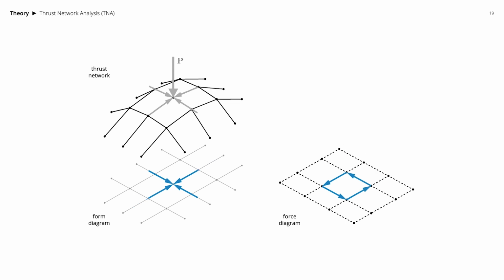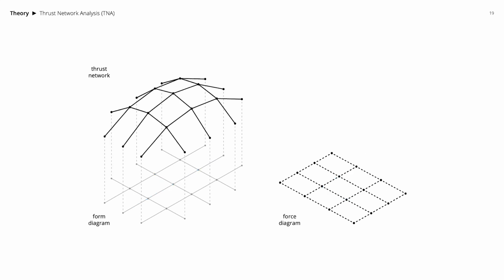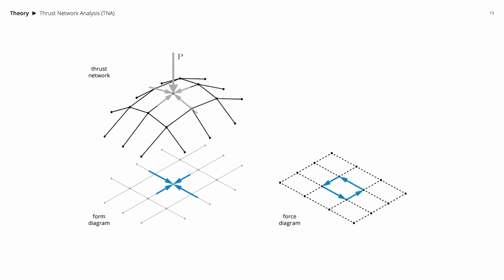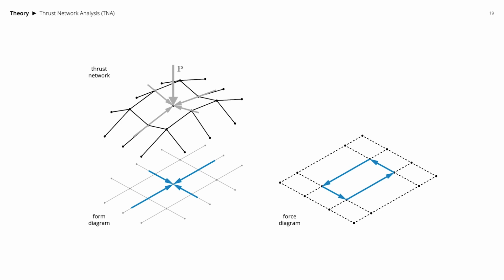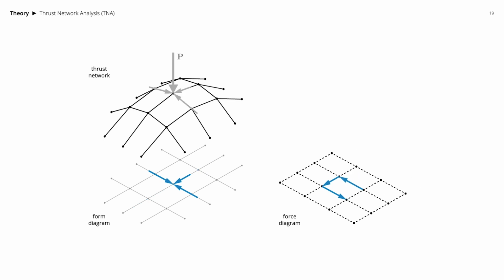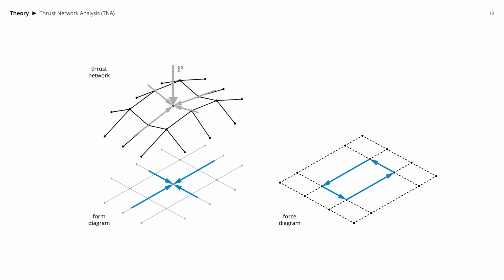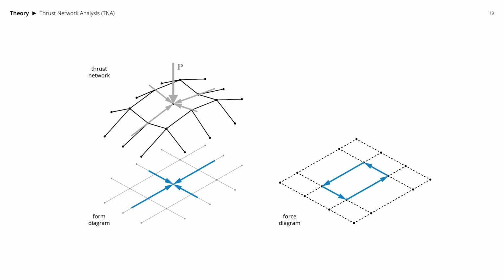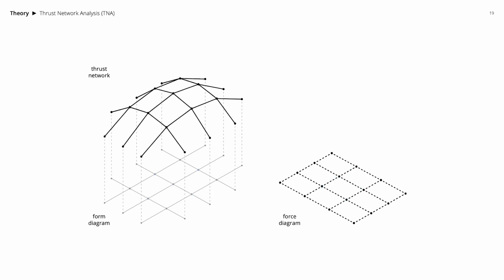In contrast to other form-finding methods based on black box numerical calculations, TNA offers the force diagram, which is not just a visualization of horizontal equilibrium of the shell structure, but also the means through which the designer can explicitly modify the internal forces, thereby enabling a careful and controlled transformation of the geometry of the shell structure, while the designer is constantly being informed of the internal force distribution.